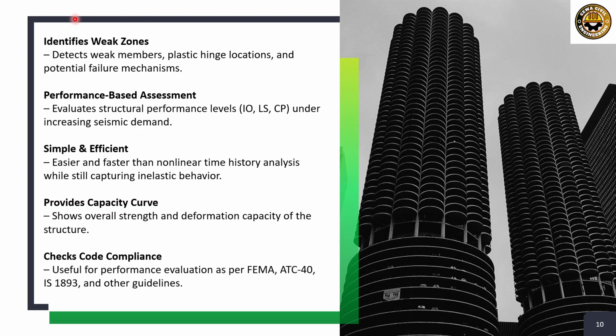First of all, when we talk about Pushover Analysis, it mainly identifies weak zones. In case of linear static analysis, we do not get this kind of identification of where the weak zones are. Yes, we have a basic idea, but we do not understand what kind of deformation and behavior there will be at the weak zones. So it detects weak members, plastic hinge locations, and potential failure mechanisms.